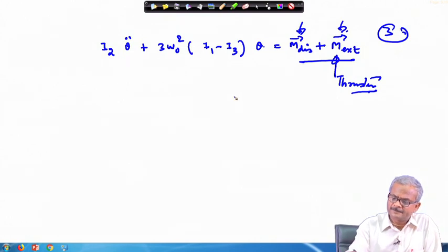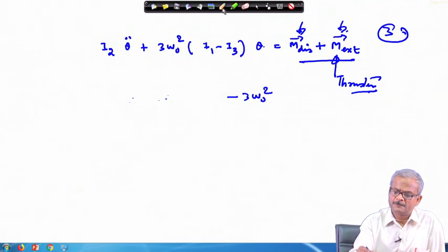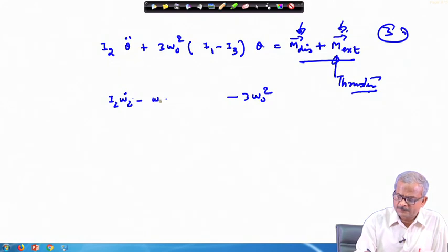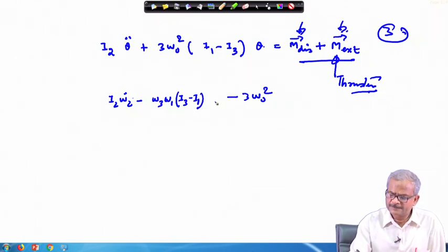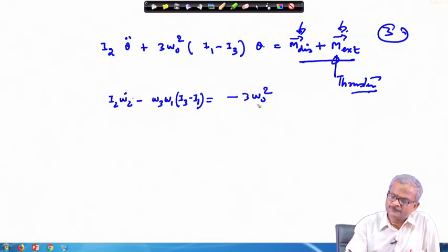And the gravity gradient part, if you remember, we have written like this. If it is I 2, so we had I 2 times omega 2 dot minus omega 3 omega 1 times I 3 minus I 1 on this side, and on the right hand side then you had the torque terms due to gravity gradient, external one, whatever they were.